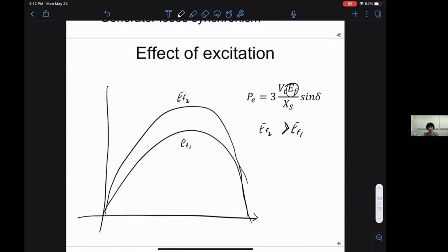You could change this excitation voltage in the system, but normally you have a fairly limited range to pick from. The range of the excitation is not very large. You can change the voltage a little bit, but not dramatically up and down. This is also hard, as the feedback loop on the voltage can be complicated. So often you still want to make sure that your angle is much less than 90 to operate at a stable operating point.